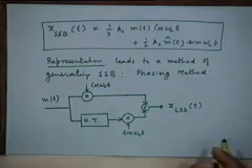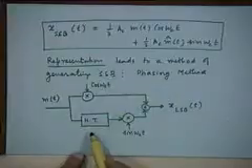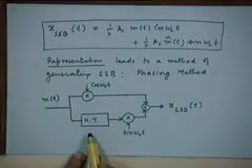So this is the second method. In the first method you required high Q tuned filters around the carrier frequency to remove one of the sidebands, right? In this method it looks very simple, but actually the difficulty still remains. The difficulty has been passed on from realization of a high Q band pass filter to an ideal Hilbert transformer, right?